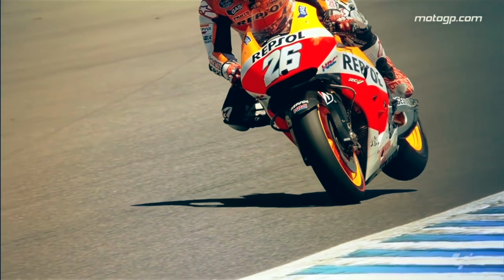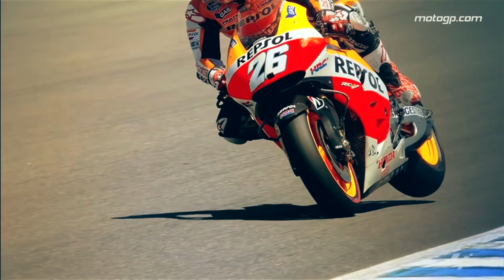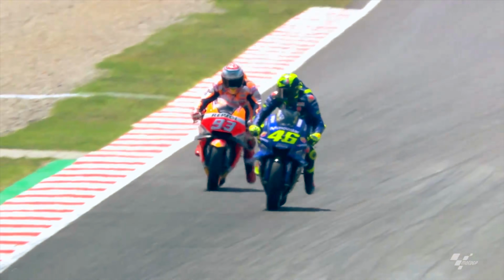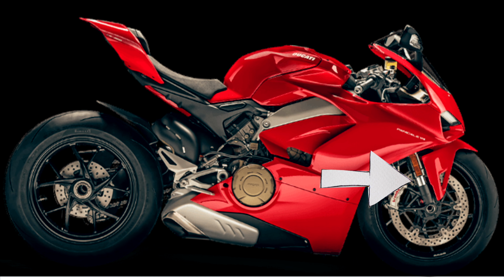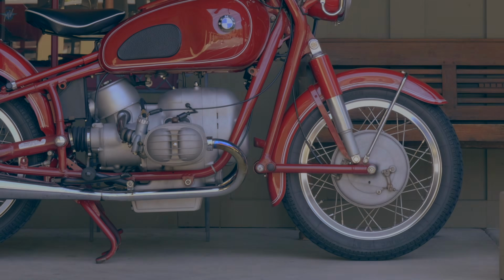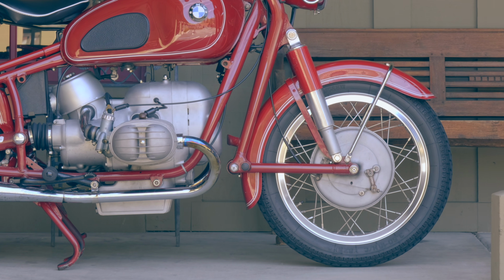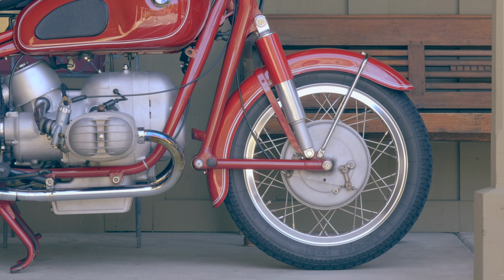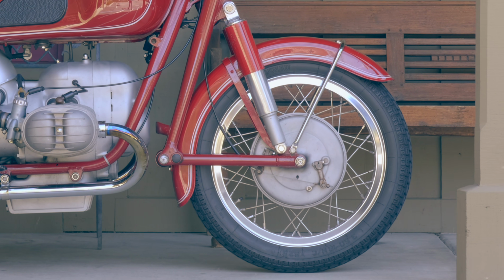So, braking with an upside down or conventional fork will have the effect of decreasing the wheelbase of the bike, making it unstable but easier to steer. Secondly, as the fork compresses, they run out of travel, and thus their ability to travel over bumps decreases as the fork tubes bind and static friction takes over. This effect is called brake dive, and is a very important attribute that one must consider when designing a suspension system. Some older viewers might be thinking to themselves, wait a minute now, didn't engineers solve this problem with brake dive a really long time ago?